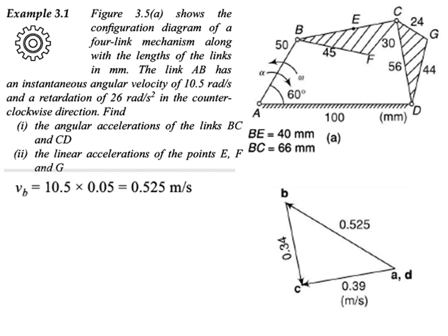So it is given in the counterclockwise direction. Okay, so it will be perpendicular to this in this direction. So you start with this A to B. Okay, A to B, and the value for this can be calculated by taking omega into length of AB. So 10.5 into 0.05, that is in meters, if you take, you get 0.525. Okay, so you can draw a line perpendicular to AB.